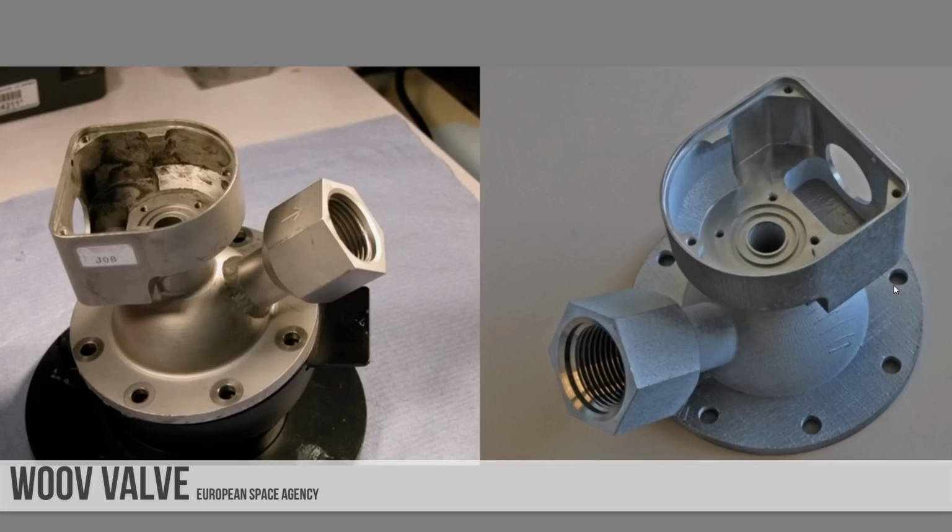Because they went over to 3D printing and they eliminated a lot of the machining and the welding, they could use a different material. So this is a grade 5 titanium, Ti-6Al-4V. And that change in material alone reduced the item's mass by 40%. So the design is exactly the same, but the material density has been changed. And so we have an overall weight reduction of 40% on that part. No welding involved.